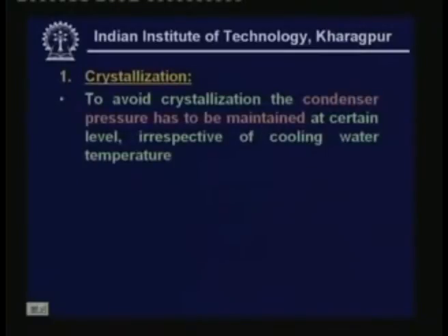Crystallization, as you know, happens as a hot strong solution is cooled. When a hot strong solution is cooled, you will find that at a particular point, if the inlet pressure is not very high, the exit condition or the solution condition may enter into the crystallization region. Once it enters into the crystallization region, solid lithium bromide crystals are formed, which you want to avoid.